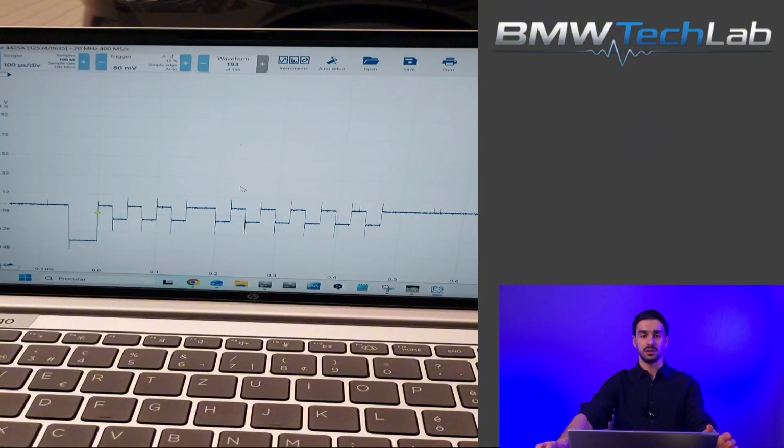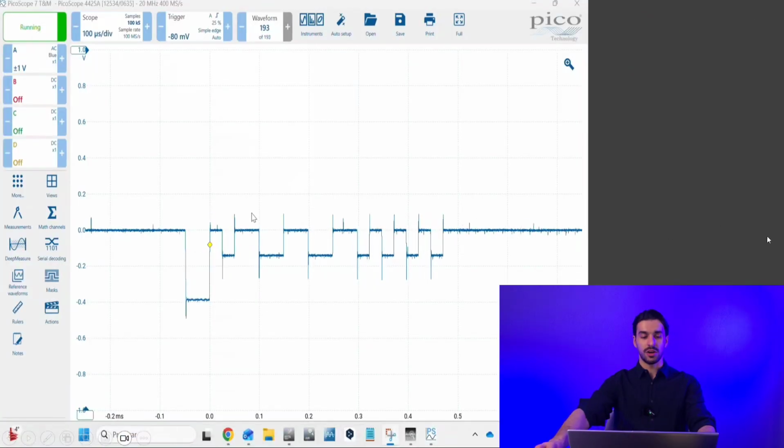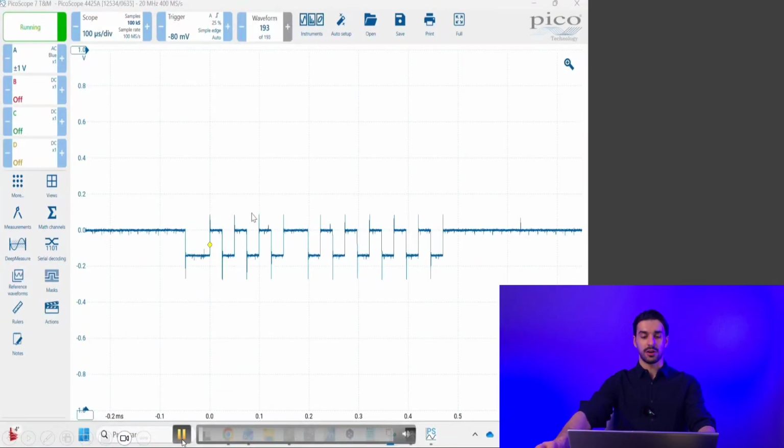It's not a short circuit, it's not a miss ground or a miss positive. The sensor is working fine. The only thing is it's not recognized that the wheel is turning. And this is why we don't get the fault. It's normal, and now I understand why it's so important to connect the scope, to try to understand how the sensor works and why the car doesn't set the fault for the sensor. This is really important. So here I show you how the car recognizes when the wheel is turning to the front, to the rear, or when it stopped.